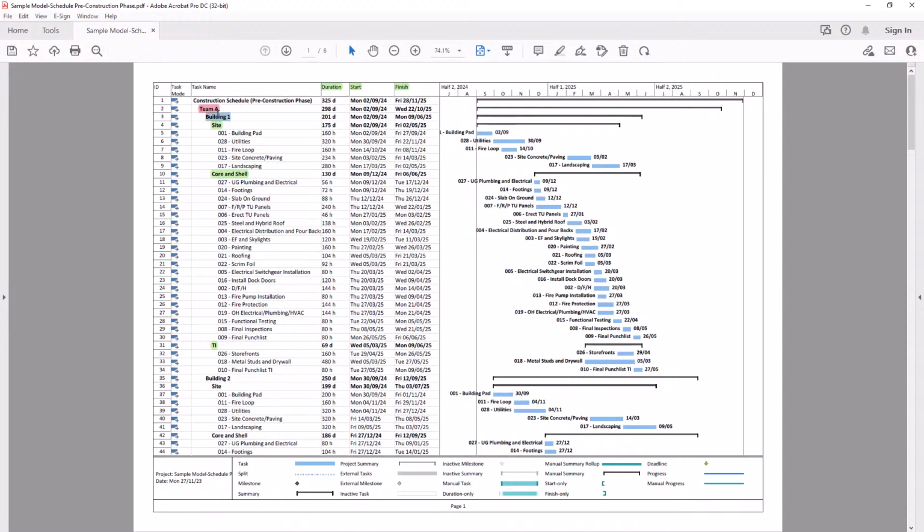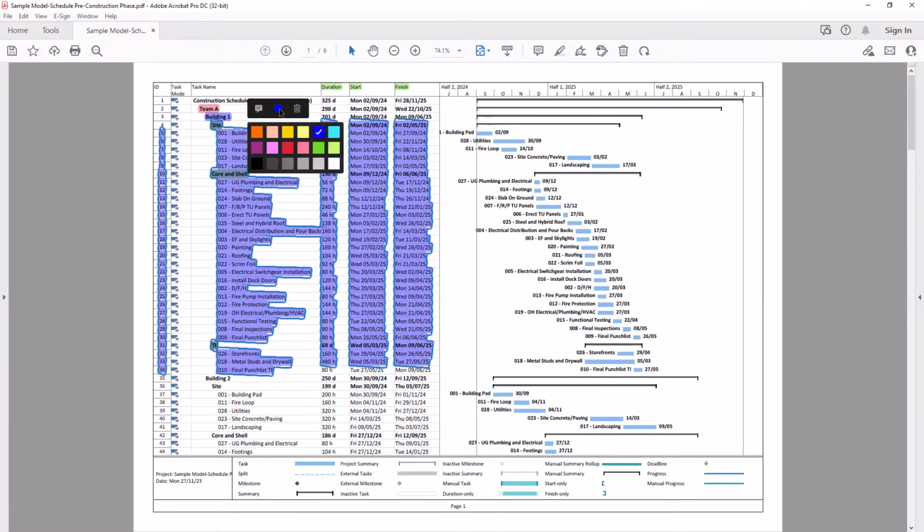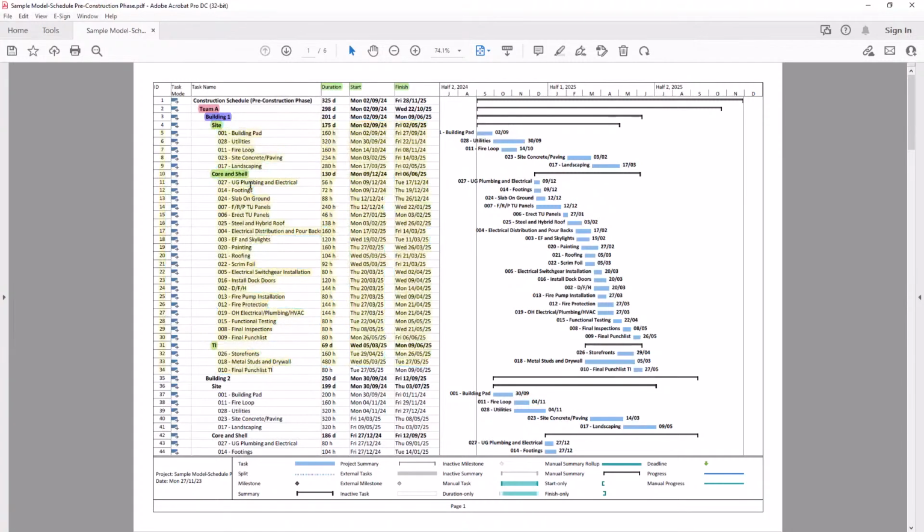Selection sets for buildings, we have 7 buildings. Selection sets for zones, we will see how many zones we have for each building. And finally, selection sets for classification. I think it is clear what will be included in the first 3 groups of selection sets we will create, related to teams, buildings and zones.